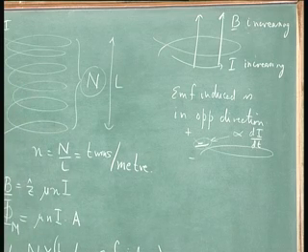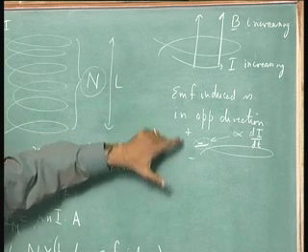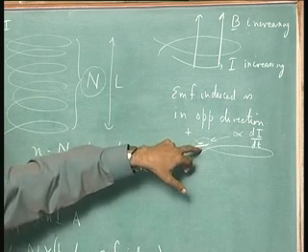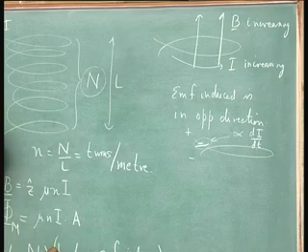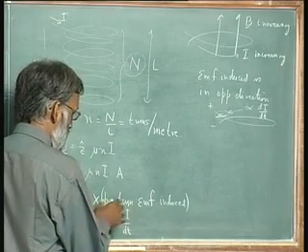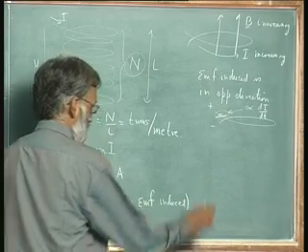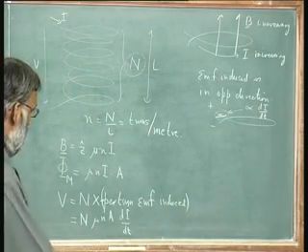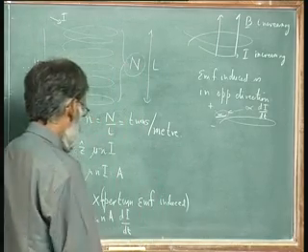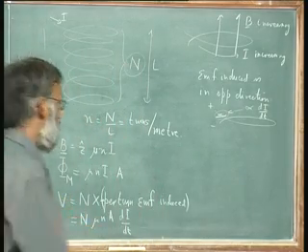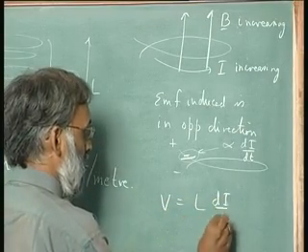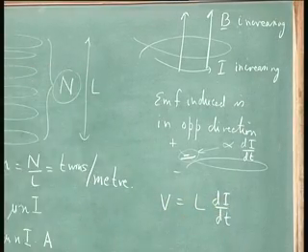So, this voltage is therefore in the plus direction. It is in the plus direction because I have to overcome a minus voltage. So really I should have a minus sign here, indicating that V is N times the negative of the per turn induced EMF. So overall a positive sign results. But this is nothing more than inductance. So this is nothing more than saying V equals L dI dt.